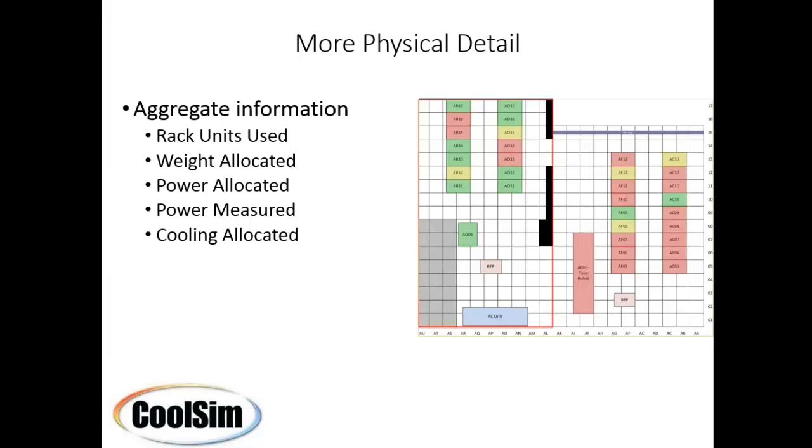But we do have the ability to read any SNMP managed sensor, whether it be in your Liebert unit or some other AC unit, or whether you've got your sensor in an intelligent power strip or something that's standalone. As long as we can get to it SNMP, you can add it in. So you can do temperatures, power, cooling. Yes, we can pull actual load for electrical, and you can also get your temperature and humidity.